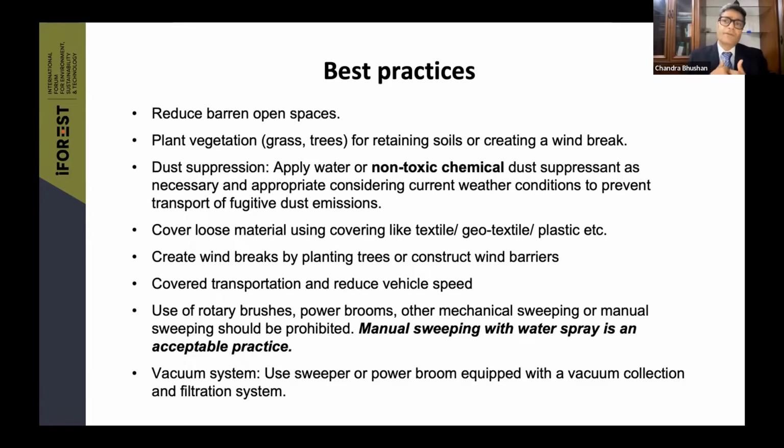Then you can use dust suppression technologies. You can apply water. I think many people of my generation will remember, I come from a small city, that before brooming, cleaning the roads, water used to be spread on the roads so that less dust is generated. So go back 10 to 20 years, and application of water was done on the roads to reduce dust. So water is still a dust suppression technology. If water is available, recycled water is available, it can be used as a dust suppression technology. But now you also have non-toxic chemical dust suppression, which can be used, and I will discuss it in a little more detail later.